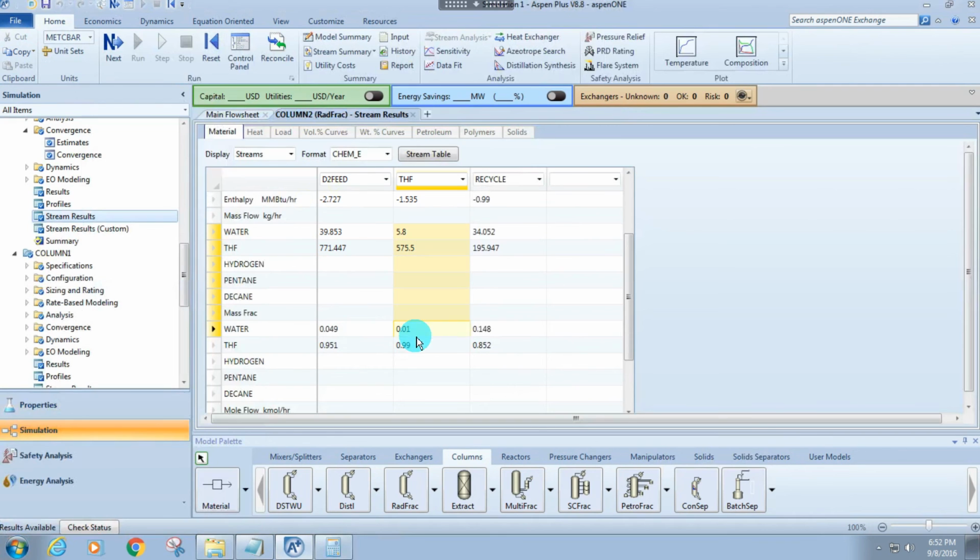So that's how pressure swing distillation works. And with your components in the project, there will be quite a few azeotropes. Some procedures like this can help you take a step back and decide what to do first. Are you going to treat the benzene azeotrope first, the toluene azeotrope first, and things like that.